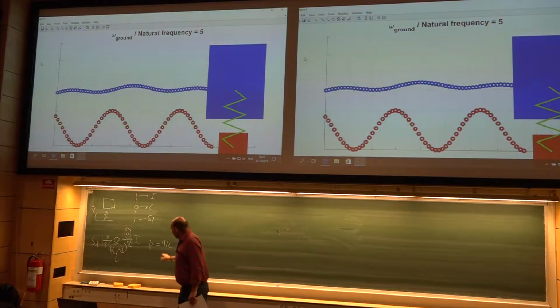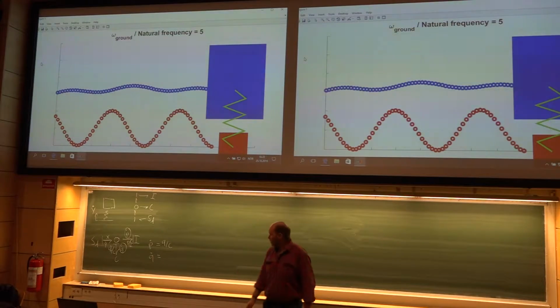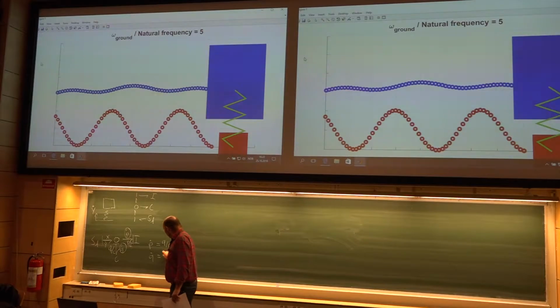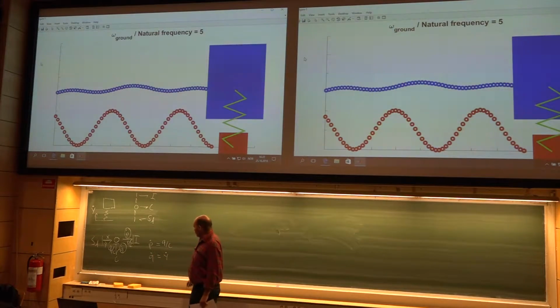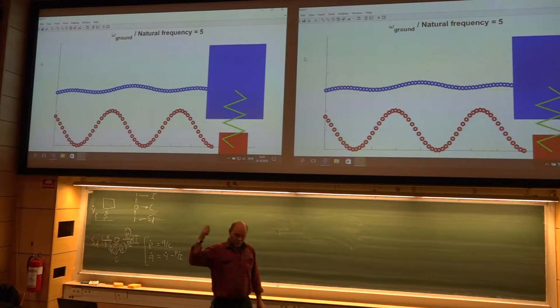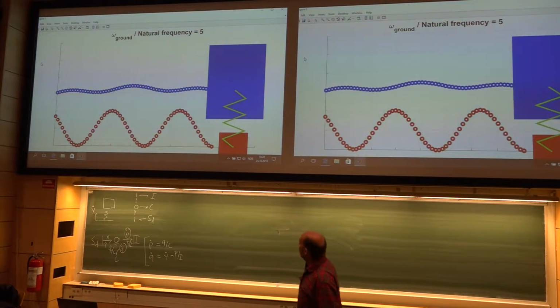And the other one, q dot: well, you use the summation rule around the zero junction. What comes in equals what goes out. So here we have the given flow source minus p over I. So these are the two equations that we now simulate in this program.